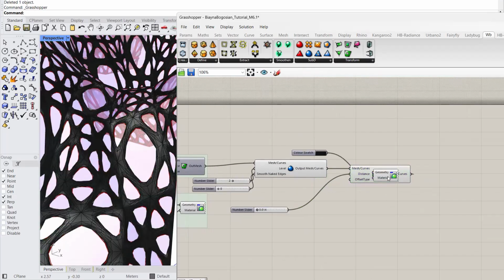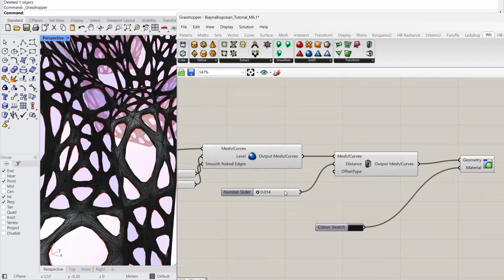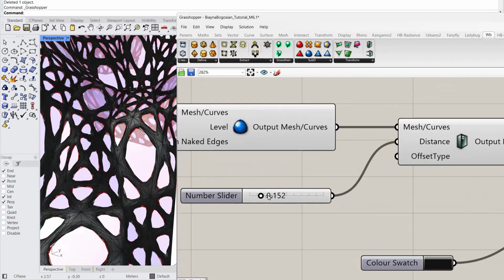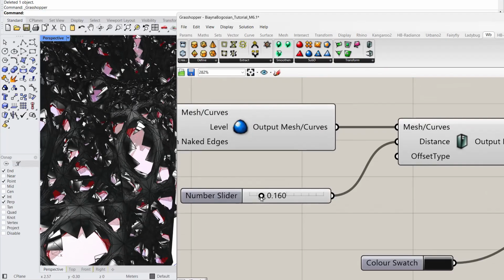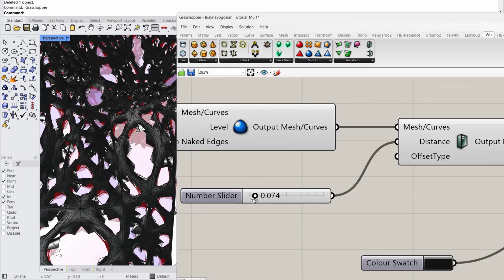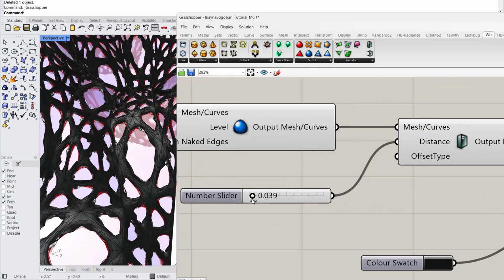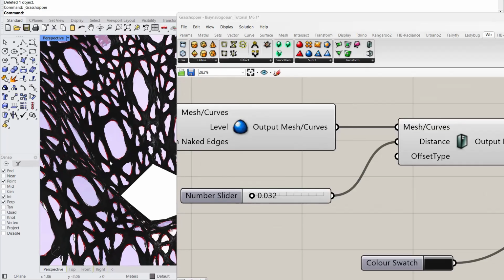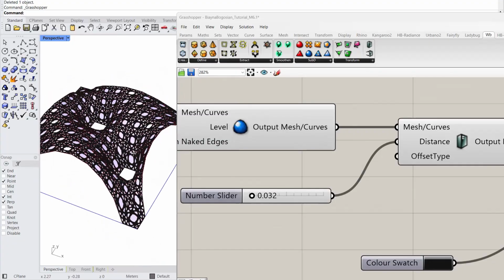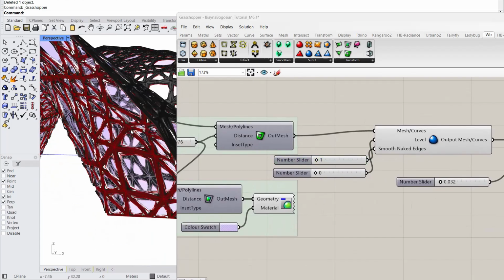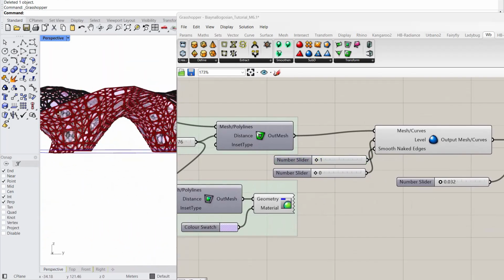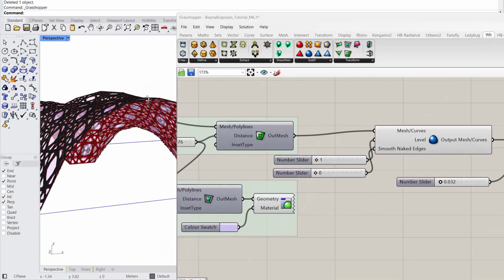And then last step, we're just adding thickness. That's if you want to 3D print. Now with complex shapes like this, if you're providing too much thickness, it might start to overlap. So I think this is where we need to be kind of careful, depending on the outcome. Maybe it would be better to keep this a little bit thinner. So if I were to increase the size, definitely you'll have less chance of these kind of interrupting, but we're not really going for anything specific.